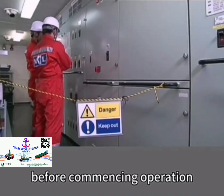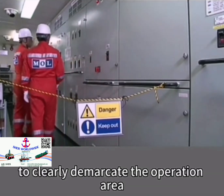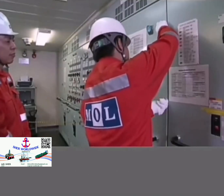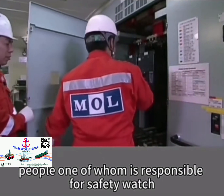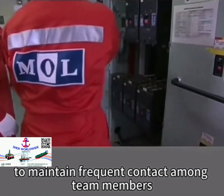Before commencing operation, secure the operation area with ropes and/or warning signs to clearly demarcate the operation area and accessible areas. Inspections must be conducted by teams of 2 or more people, one of whom is responsible for safety watch. Use signaling and other forms of communication to maintain frequent contact among team members.